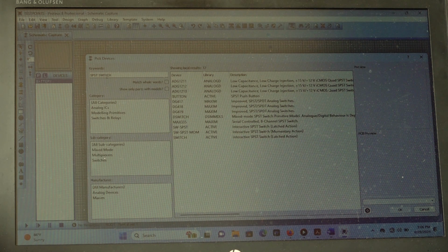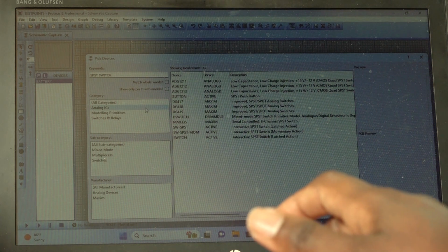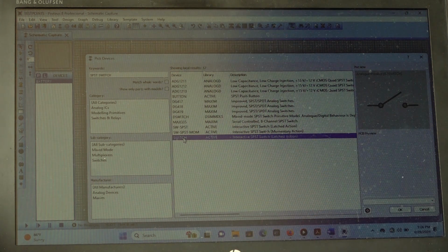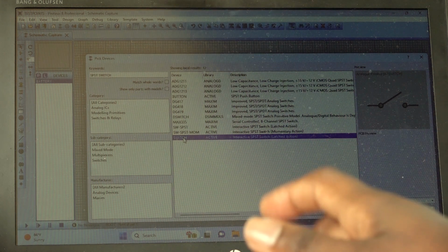Then again, if you see this switch, it's been written active. If Proteus did not open well, when you search the switch, you won't see that active switch. So the indicator that maybe you have made some mistakes on opening the software is in case you are missing some active components that you know in your mind that they should be active. Are we together, class?